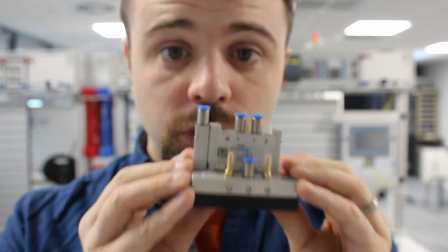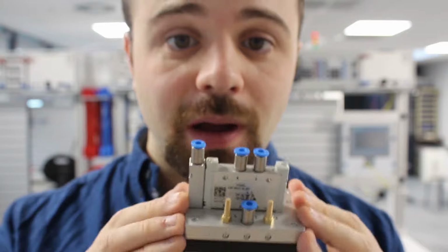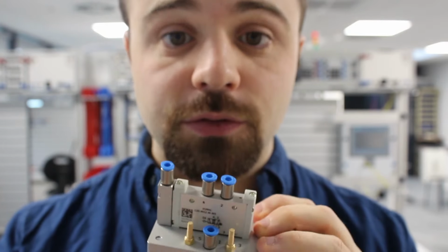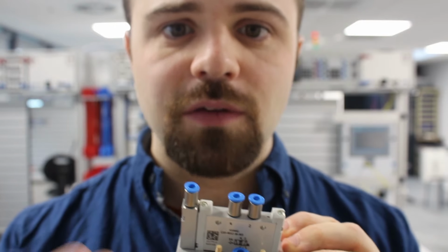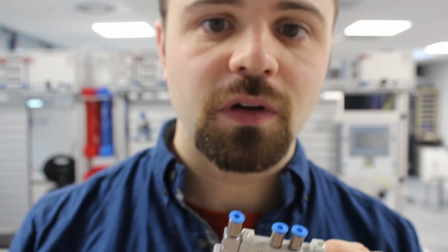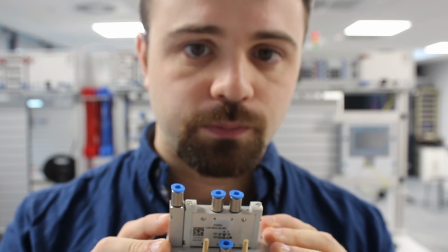For the next part of the video, we're going to start looking at directional control valves. So it's important that we can see exactly how they work, hence the close-up. This is a 5/2-way directional control valve. It's called that because it has 5 ports and it exists in 2 ways or states. If it helps you to think of it as a 5-port 2-state valve, then you can do that. But we normally refer to them as 5/2-ways.